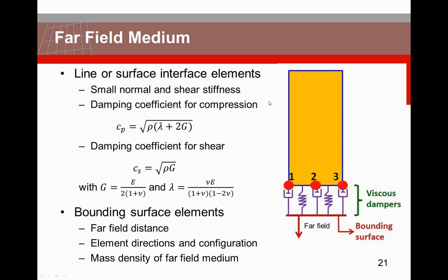What normally will happen if you do nothing special is that when a wave is traveling downward and there is just a normal support here, the wave will be reflected and will travel up again and will remain in your model. This is probably not what you wanted, because in reality a wave that is somewhere started will go on and will move out of your model.